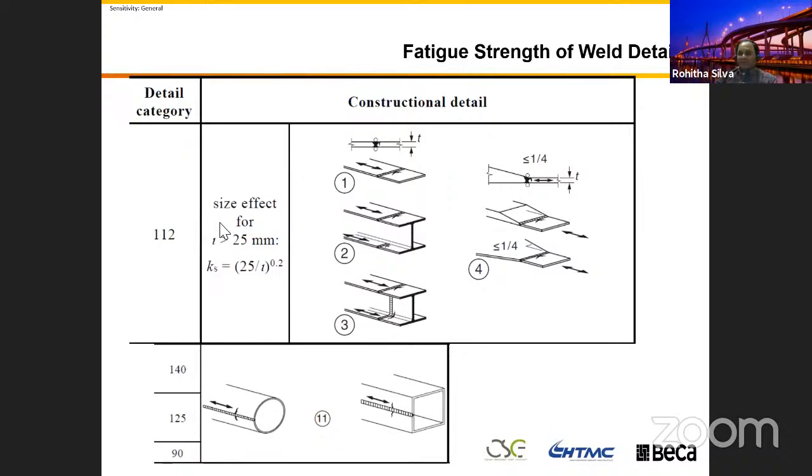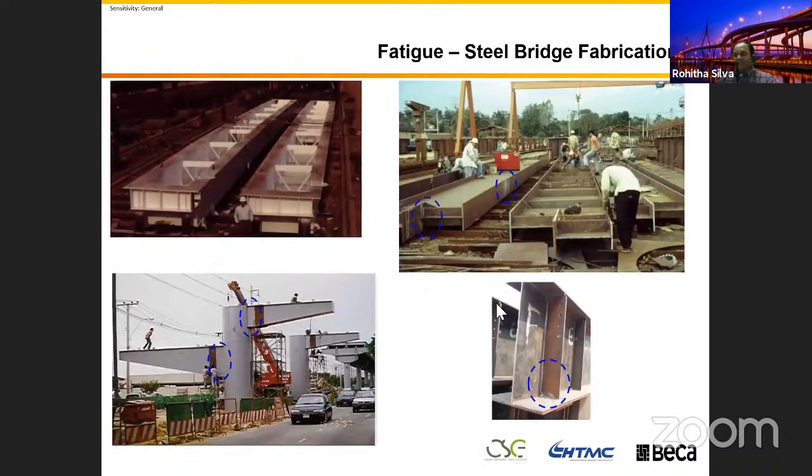And then your detail, the corresponding fatigue strength is 112 for 2 million. The 1 million we say is 50% higher than that, right? Let's say 150. Then you make sure that your corresponding welded detail, these two plates assembled together, your fluctuating stress due to traffic load is less than 150. That's the way you need to make sure.